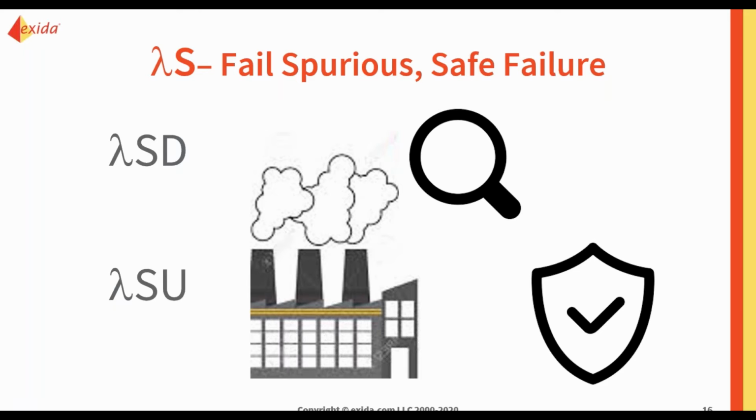But you're in normal operation, everything's going fine, and it shuts down unnecessarily. So even when nothing is wrong, your process is running normal, your emergency shutdown system kicks in and takes you to that safe state. And that's not good.